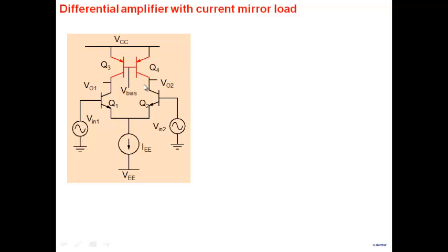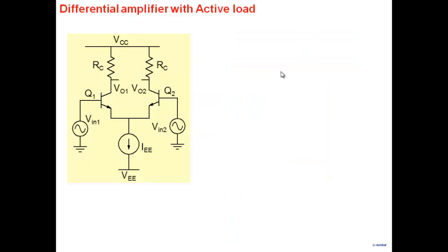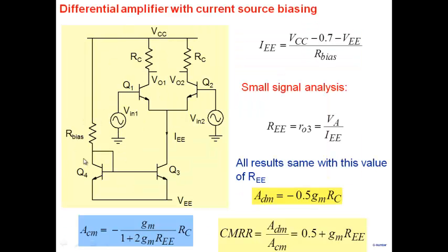In order to solve that particular problem, let's look at this solution here. I just pointed out that V bias is very sensitive. So what we've done is, we've taken V bias, this point here, and connected it here. Can you see that this circuit is also like a current mirror? Just go back and see a current mirror circuit. When you see two transistors, where one transistor's base and collector are shorted together and the two transistors are matched, this is what we call a current mirror.